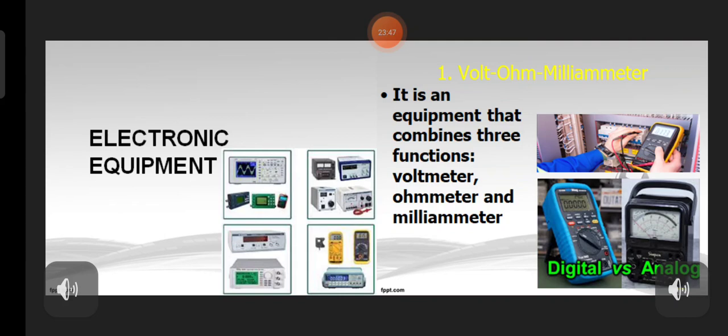As safety precautions in the maintenance of this instrument or equipment, the following should be observed. Always rest the function switch at 250 volts alternating current if an off position is not available in the instrument. For current and voltage measurements, always set the function switch in the correct setting, which is a little higher than the expected current or voltage present in the circuit. Place the instrument in a cool, dry place, away from any magnetic devices, and free from vibrations.